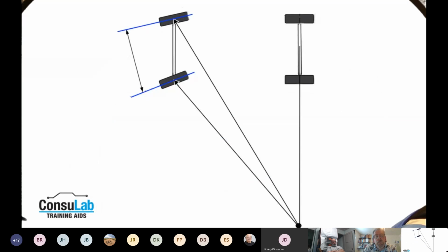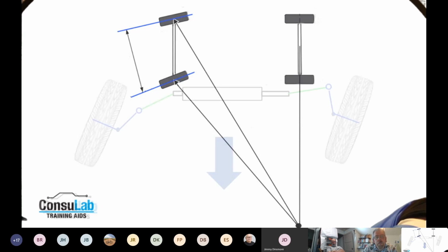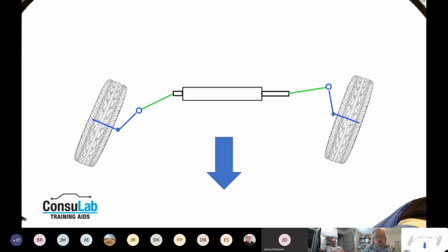As we drive this four-wheeled vehicle around a corner, though, all of these wheels and tires travel in a different arc. And this is, again, standard things that we always teach when we're talking about alignment. But all of these have to go in different circles. So the reason that we build those arms at an angle is that the math of it and the geometry actually causes a slight toe out on turns to reduce the amount of slip.